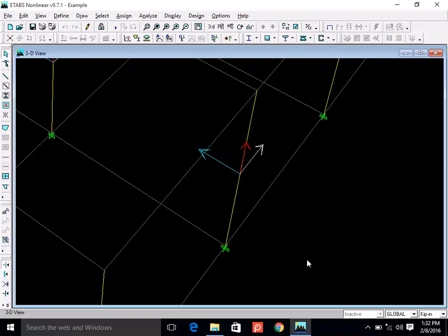Now bending moment. Again, because you have gravity loads on the beams mostly, bending moment is either like this in the midspan or it's like this on the support. Both of them are about which axis? It is about axis 3. So gravity loads are producing bending moment about axis 3, and beams mostly have gravity loads. That's why M3 is important.